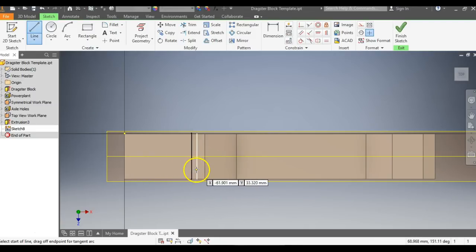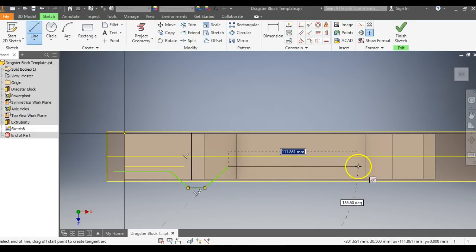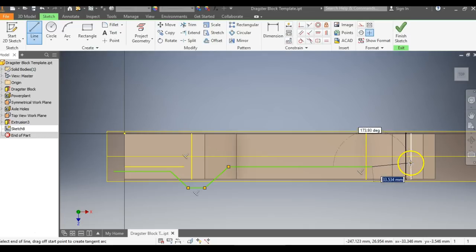I want to know where my power plant is, and just as important, I need to know where my CO2 car's axles are. And I don't want to ever cut into those axles when I'm first planning out my car. So I'm going to go from here and here, here. I'm going to hit escape, and I'm going to connect up to that line, coming back to my line tool. Here and here. From there, I'm going to make a nice diagonal, and I love the rail design. I just think it's a really nice, simple design to easily make my CO2 car go fast. These must be my other power plant holes. So I'm going to go here, here, and meet up at the center of the car. Perfect.